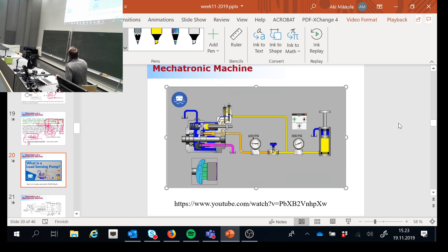So in this particular case, we've got a pump that sets its outlet pressure just slightly higher than what's needed by the load. We've got to have some kind of a flow controlling device in there. This is our needle valve that's being used to set our desired cylinder stroke speed. But let's have a look at what happens when I add a brick to the brick stacker. Our load pressure has gone up to 600. But what happened to our pump outlet pressure? Somehow it automatically adjusted from 600 up to 900.